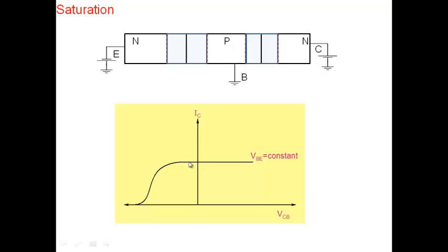It's as if it doesn't really matter, because the forward bias on the collector base junction is 0.1 or 0.2 or 0.3 or 0.4. Nothing really happens. Once the forward bias on the junction becomes significant, then you start to see that the current is dropping. The current begins to drop quite sharply and may go to zero. And if I go further, it may become negative also. All right, so that's the behavior.